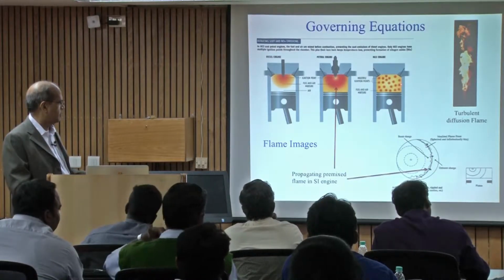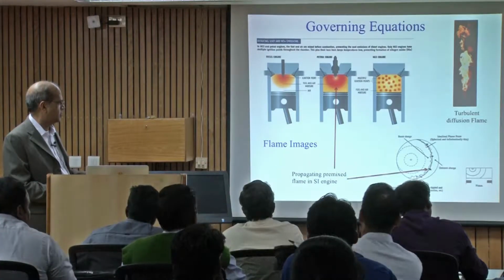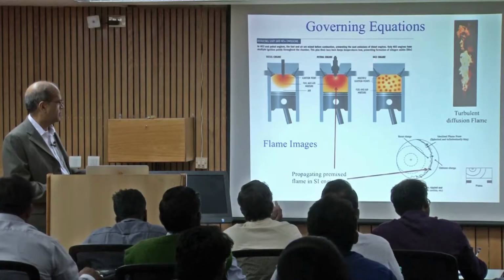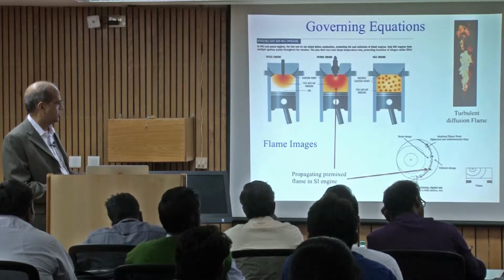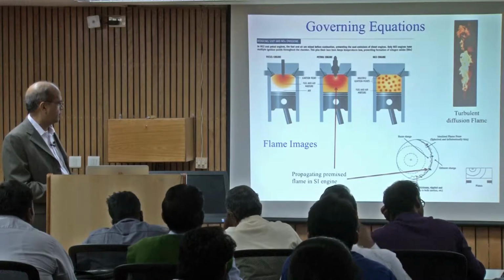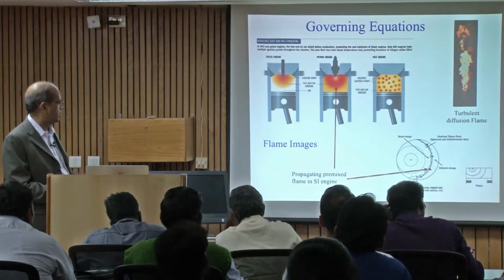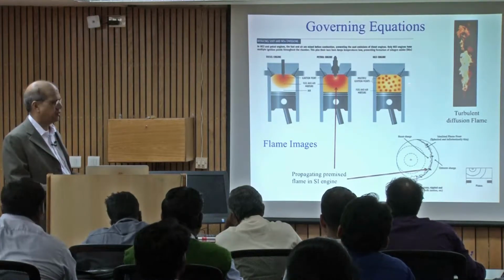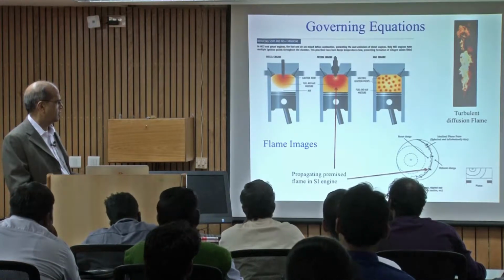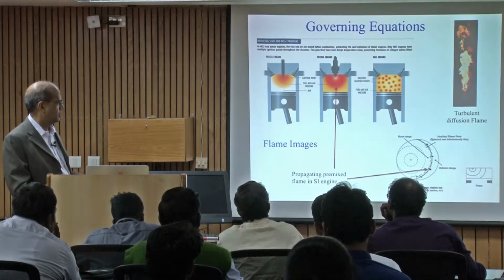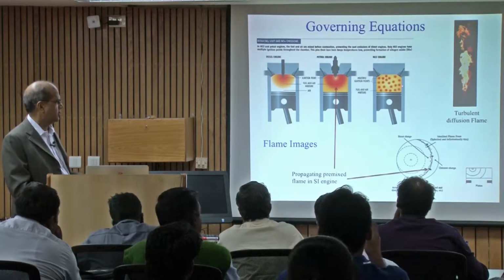Okay. The mixed combustion mode, in more recent years there has been a lot of work in this. It's called the HCCI engine, homogeneously charged compression ignition. So here what you do is one way is you inject the fuel. It's like diesel engine combustion, but you inject the fuel very early. Okay, so the piston is far back. So you inject, and then the fuel vaporizes, and it mixes. Okay, and then the ignition is almost like everywhere.